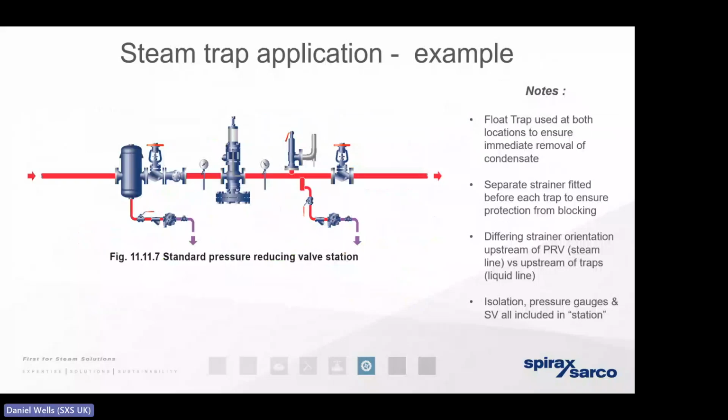We've spoken about the importance of those steam separators previously. A steam separator removes the moisture from the steam to protect certain components such as control valves, pressure reducing valves and flow meters from the effects of erosion. So we need to ensure that we've got a trap with a really good capacity, preferably a float trap, to drain that condensate away. And we also want to ensure that we've got an appropriate steam trap located ahead of isolation valves and control valves.